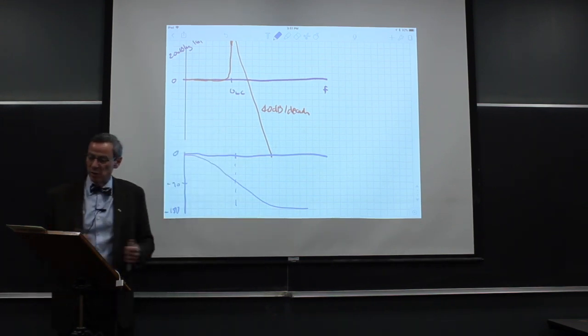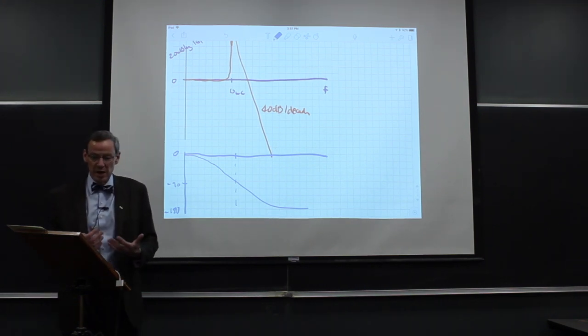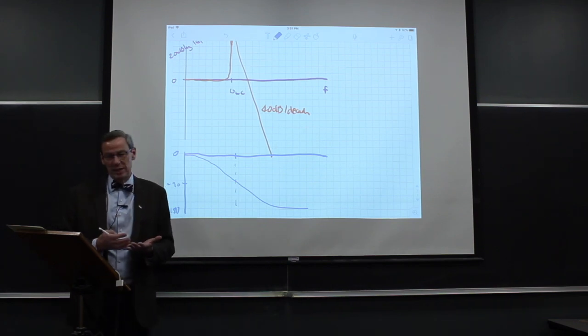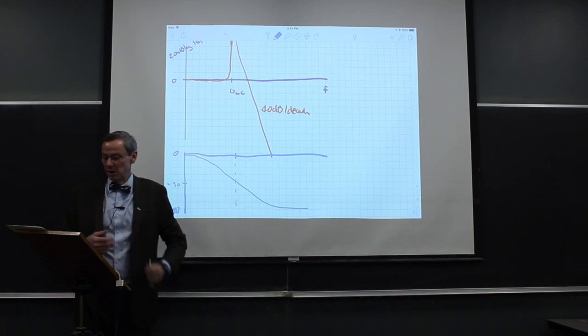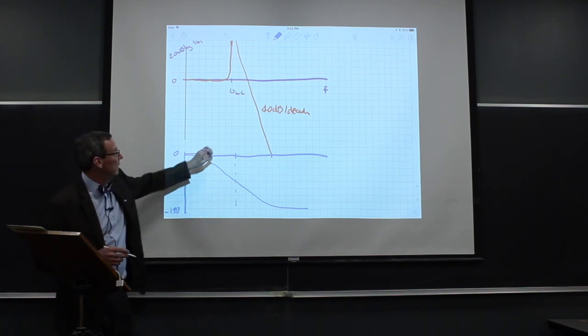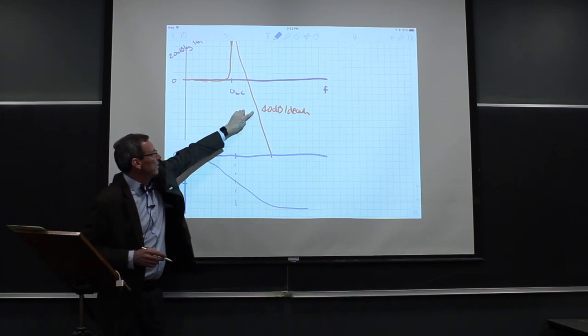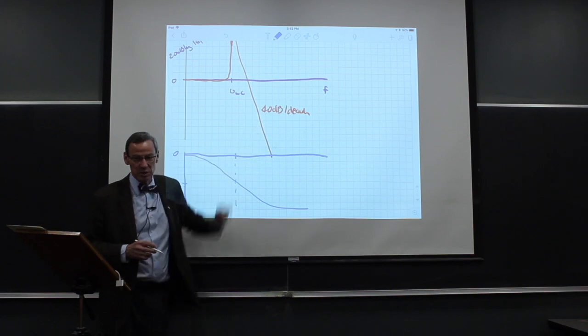So that's basically what happens with an RLC circuit when we look across the capacitor. We could look across other components, and we can actually invert this and create notches instead of amplification at the signal. You can do a lot of interesting things with an RLC circuit. The key thing is that eventually the gain will fall off at 40 dB per decade, like frequency squared.